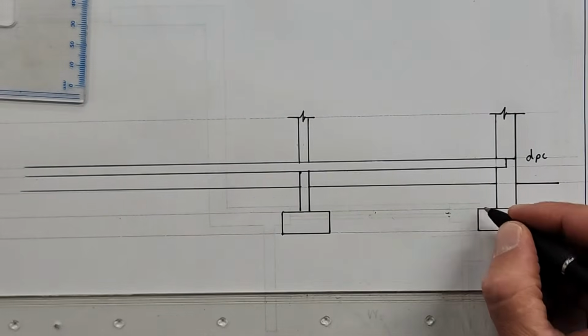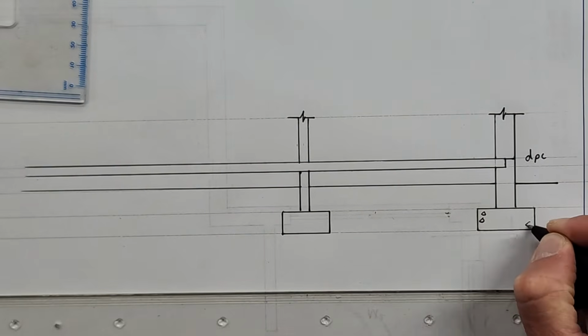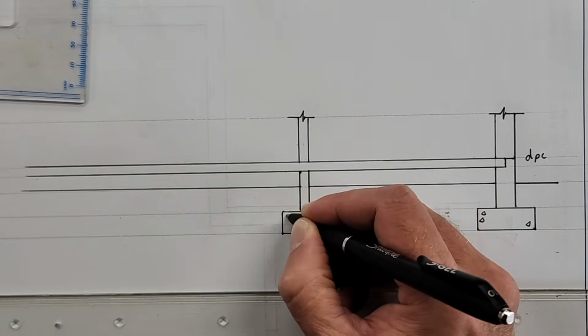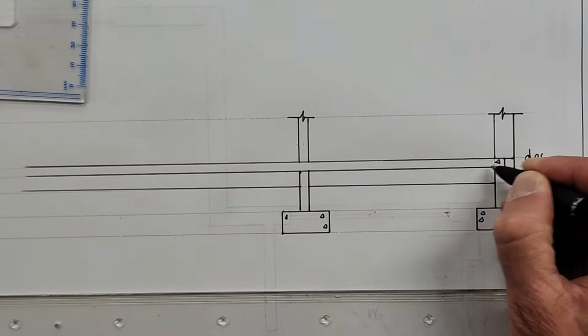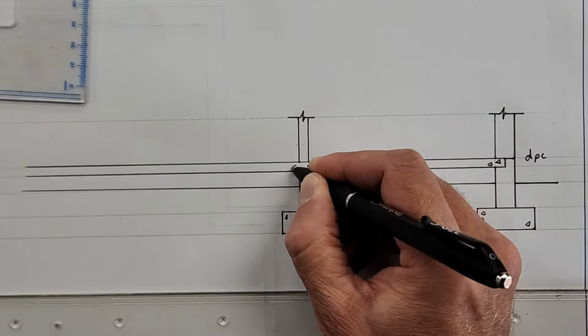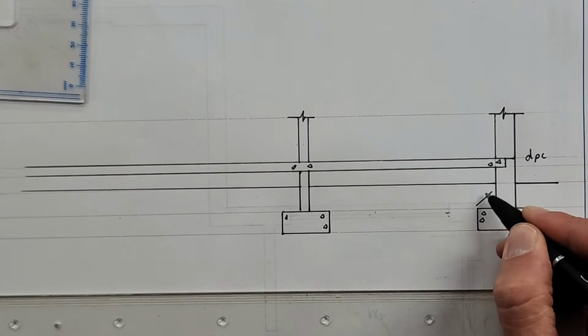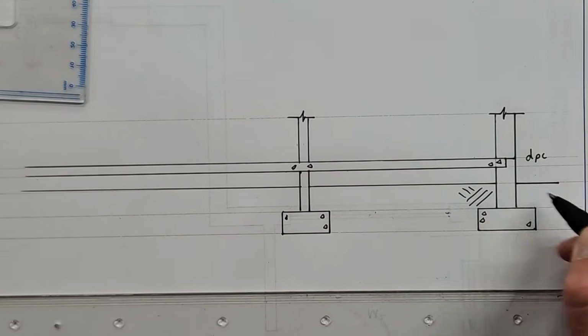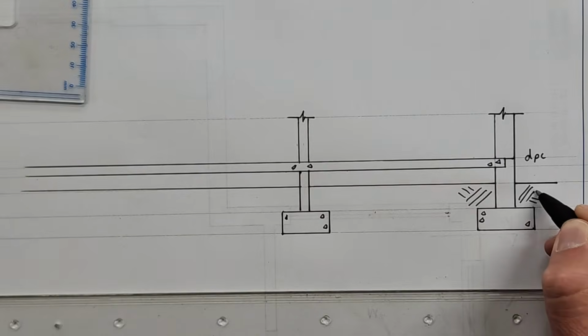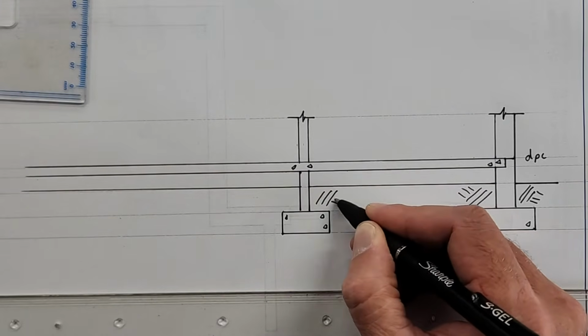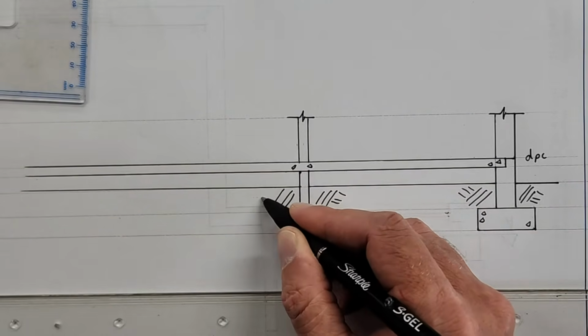Okay, what's the hatching like? There's a triangle in the foundation. Same here, just 2 or 3 of them. Also in the concrete at the wall, 2 or 3 triangles. Then we have undisturbed soil on the inside here, 3 lines. On the outside, 3 lines. Same here, 3 lines. Same here. It can be done freehand.